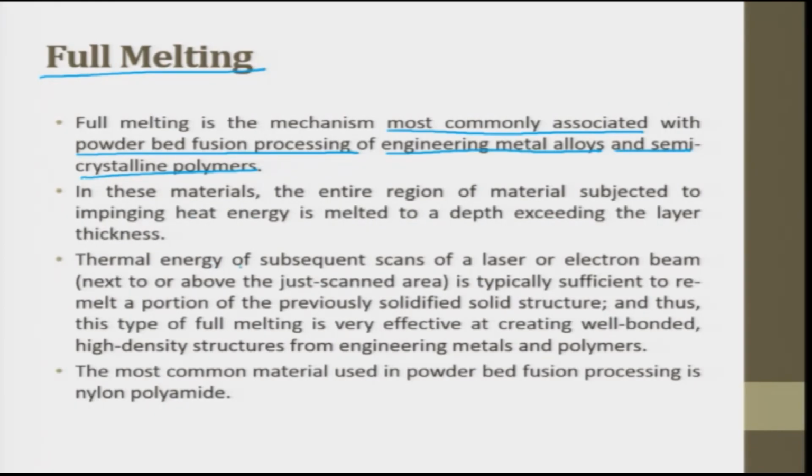The thermal energy of a subsequent scan of the laser or electron beam is typically sufficient to remelt a portion of the previously solidified structure, and thus this type of full melting is very effective at creating well bonded high density structures for engineering metals and polymers.